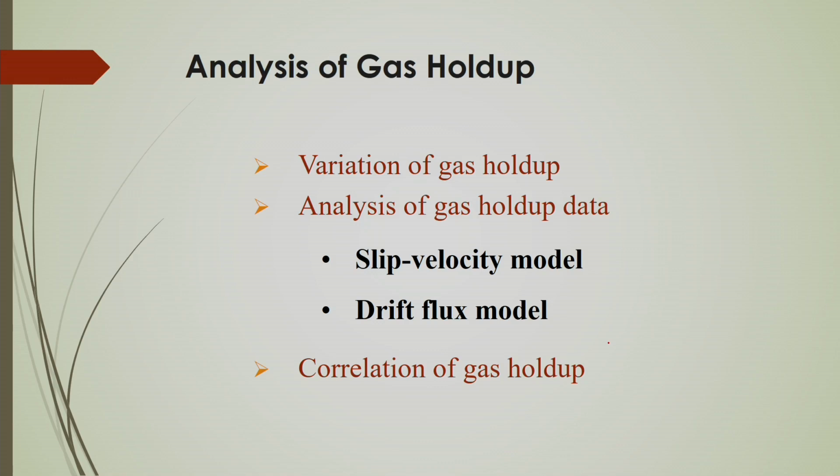You can say that this gas hold up will depend on how the entrainment happens, what the minimum entrainment velocity is, and the minimum entrainment velocity beyond which you can expect that gas hold up. This is the thing, and after getting that overall gas hold up, you can analyze it to predict based on that experimental data by a certain model.